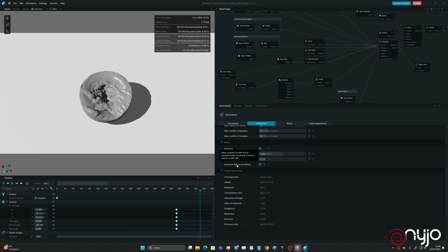By the way, we go to take the generate SDF on smoothing, so we have a better level of validation about the SDF field. And then let's see if we can have, you see, obviously, if you have no SDF smoothing, let's say that we go for 0 to the ISO value, and if we go to have the smoothing, we are going to obtain a better mesh, but obviously we are losing details.